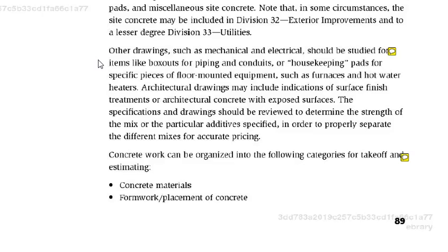And I'm not going to tell you what they're holding. You can look around on the projects and find them. So it's not just those obvious curb and gutter or flat work pages. You have to look at all the pages, and don't forget that we are building a fountain, so you need to look out there, especially for things like box outs. And you need it not only for the estimate, but also for scheduling how you bring trades into a project.